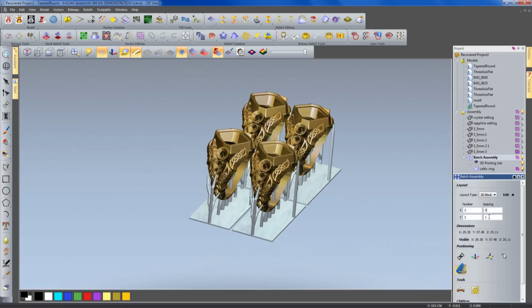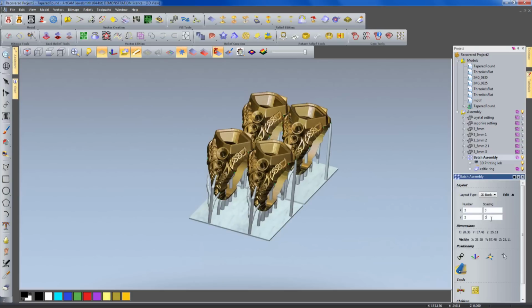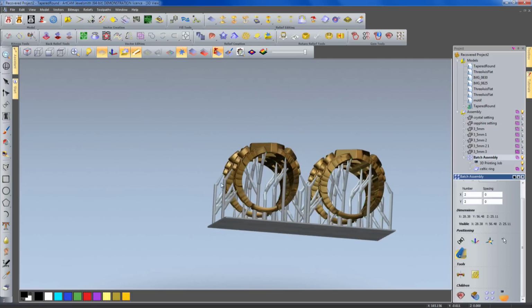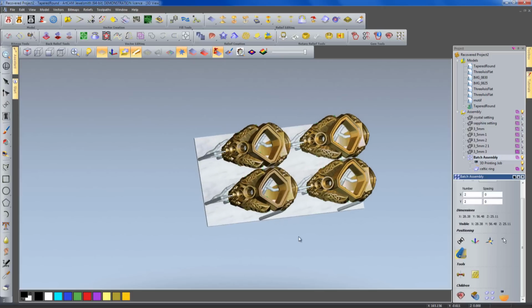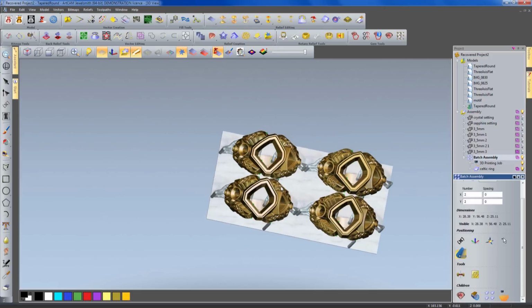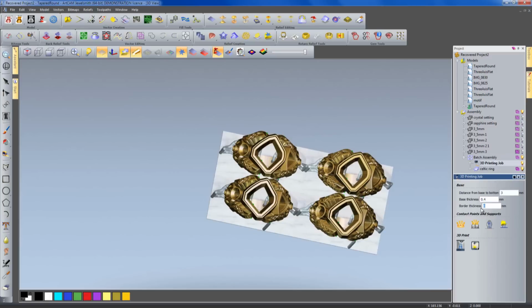So the window for the Ember is 64 by 40, so we've got 29 and 57 on here, so plenty of room. But also you can adjust the spacing here too, so sometimes it's better to build without spaces, so this becomes then one platform. We've just taken the spaces out here, and it'll probably build a little bit more accurately as well onto the machine because it gives it added support.